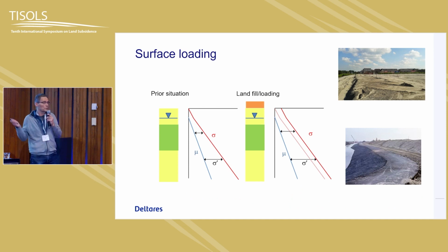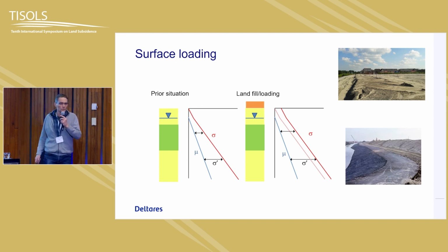In the Netherlands, of course, we have a long time of experience and our own software for predicting and modeling settlement due to loads on these soft soils. It's a huge area. The graphs show surcharges of sand put on top of these soft soils to consolidate them. On the left you see an original condition without the surcharge, and here with the surcharge. And that of course increases the total stress and thereby effective stress, starting a new cycle of compaction.